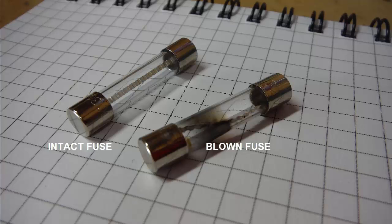intended. When opposition decreases and current reaches or exceeds a certain predetermined value for a certain amount of time, the fuse melts and the path between the two terminals opens and stops current flow by becoming an infinite resistance. The fuse is essentially acting just like a switch in series with the electrical device it is intended to protect. If the switch is closed, current will flow. If the switch is open, current will not flow.